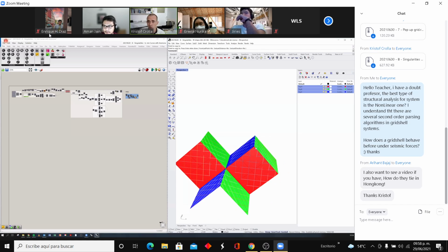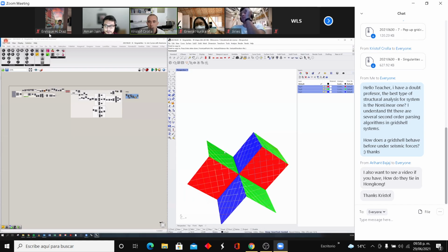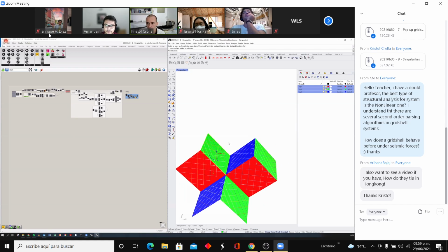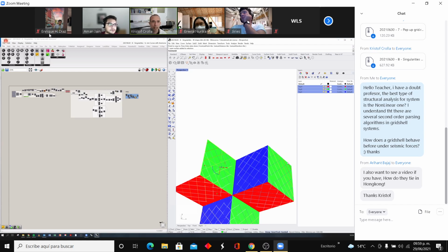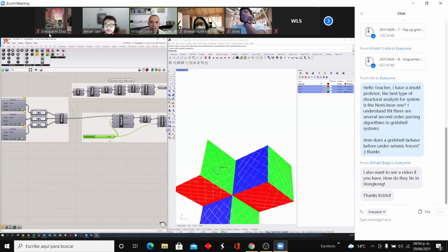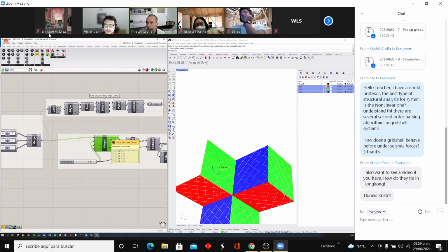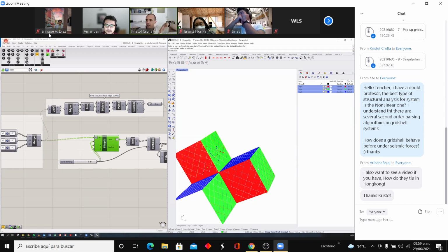An important thing to note, the orientation of these planes, it's important that they are all identical. If you would flip the orientation or rotate, say, one of the green planes, then in the beginning here, the data structure that the diagrid produces will change and the connections will be wrong. You'll start to see, not in this example here, because all the surfaces are nicely separated, but if you have a longer plane of, say, red squares next to each other, all of a sudden your curves will start to join in a zigzaggy way. So as a design restriction or rule, you need to really work with exactly these planes that you have. Any other questions or points at this point?